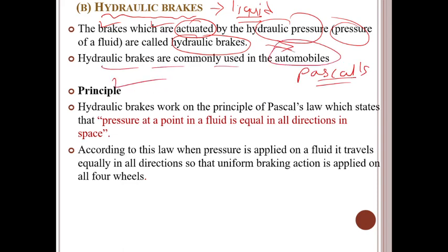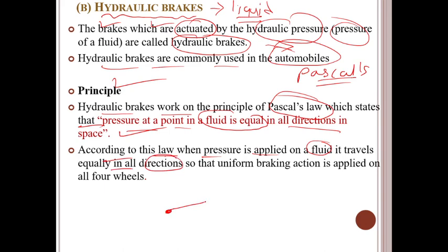So what is the principle? Hydraulic brakes work on the principle of Pascal's law, which states that the pressure at any point in a fluid is transmitted equally in all directions in a pressed fluid. This is the principle used to design our hydraulic brakes. According to this law, whenever pressure is applied on a fluid, it travels equally in all directions. Suppose you apply pressure here, it travels equally in all directions in the fluid, guys. This is Pascal's law. So uniform braking action is applied on all four wheels.